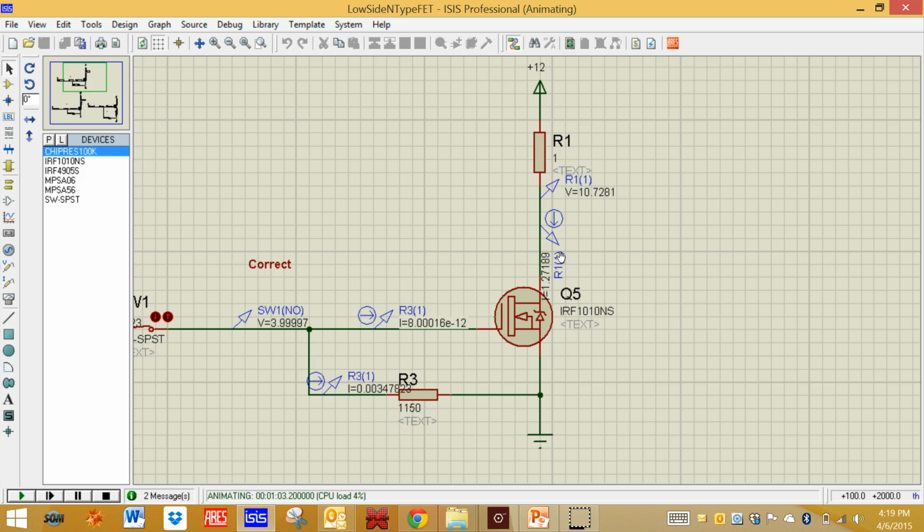And the way you would do that is you would say, add up the amount of energy going in, subtract out the amount of energy leaving, and that's the amount of energy approximately that gets turned into heat. So in this case, how much current's going in? Unfortunately I can't draw on this, but the current that's going in is 1.27. The voltage at this lead is 10.72.